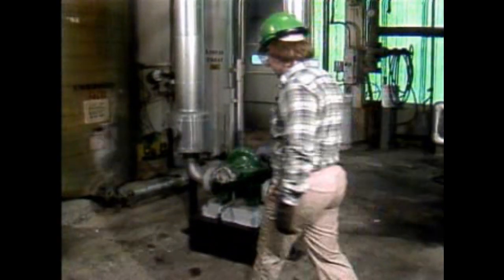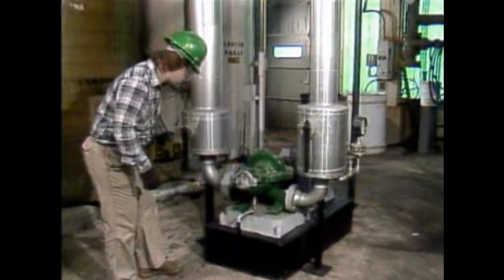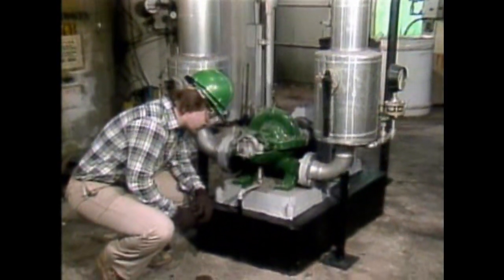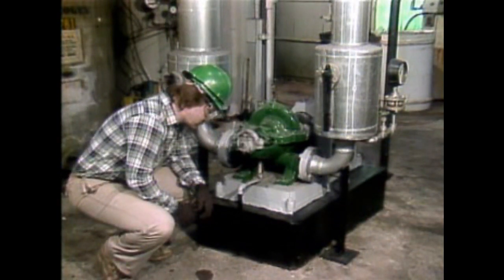This pump is running normally. The operator knows from experience that the pump sounds the way it should. Symptoms that indicate problems include excessive noise or unusual sounds. Some problems have their own distinctive sound. For example, a loud rattling or clanging sound could be caused by a broken pump part or a foreign object loose inside the casing. A howling or growling sound usually indicates worn or damaged bearings. It usually means that there's a lubrication problem. A high-pitched screeching is commonly produced by metal-to-metal contact between rotating and stationary parts.